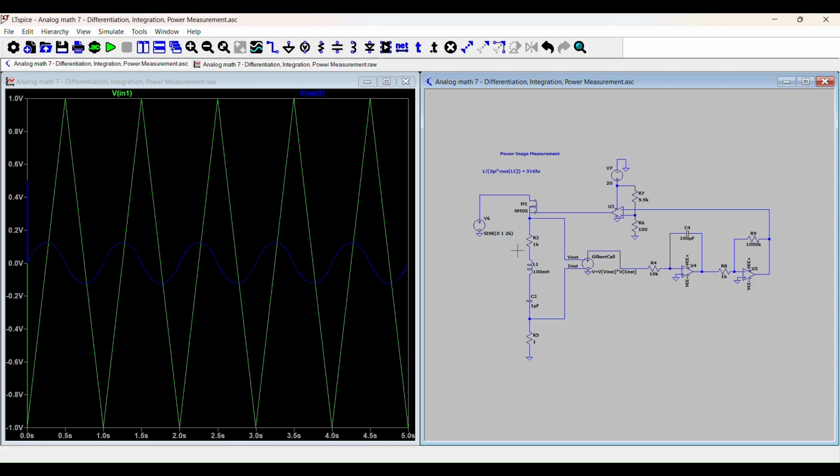So in order to actually measure power in a black box like that, you either have to measure the phase difference, which is going to be almost impossible if your signals are not perfect sine waves. The other way to do it is to measure at every point in time the voltage and current across the component and then just sum them up. That will give you the energy output, because you'll be able to capture those phase differences.